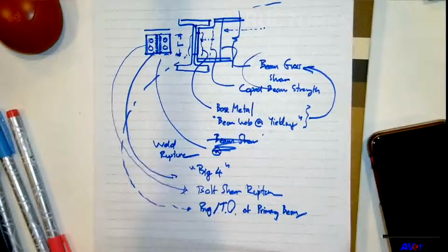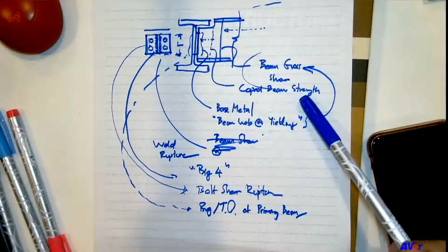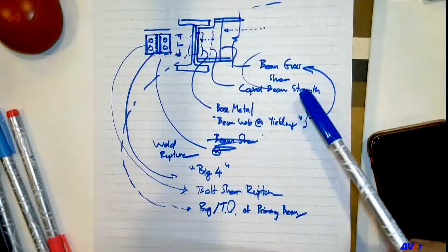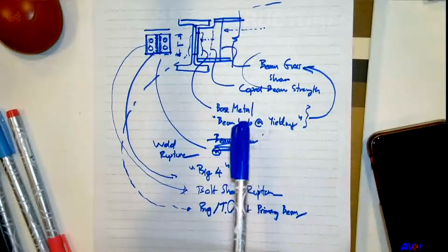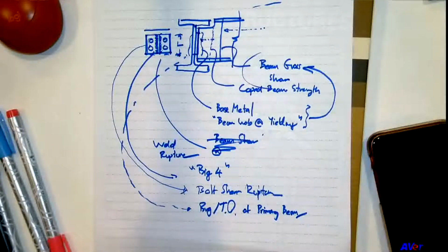All right. So you see, the calculation itself is not difficult. You know the bolt strength from that formula. This is the most complicated one with that formula. And then you calculate the base metal, that is, of course, 0.6 Fy multiplied by the web thickness multiplied by this length. And then you calculate the weld strength. It's, of course, 0.6 Fexx multiplied by 0.707 multiplied by the size of the weld, and then multiplied by